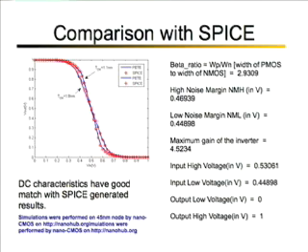I should mention that this is a 45 nanometer technology node, and the SPICE simulations were done using the BSIM models generated from another tool on NanoHub, which is called NanoCMOS. We provided the IV and the CV data to the tool PETE, and we can get a very good estimate and an exact match with SPICE.